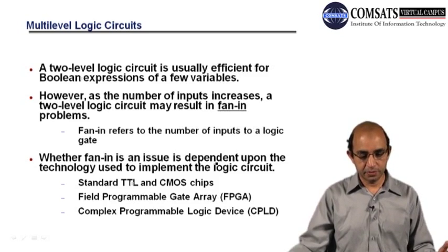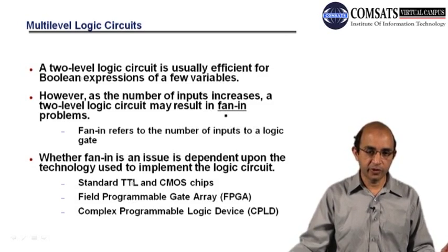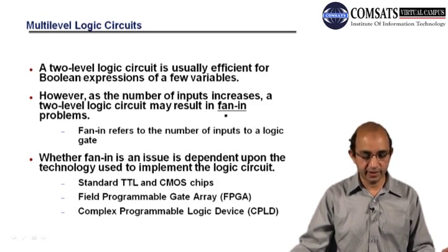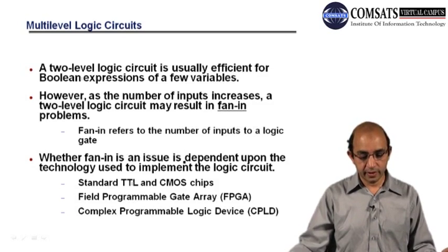On the other hand, if we have a multi-level design, that will naturally raise the fan-in. The fan-in is, if you have more inputs, your fan-in will rise. Similarly, you need more silicon area for a multi-level circuitry, and your circuitry will consume more power. There are those different issues.